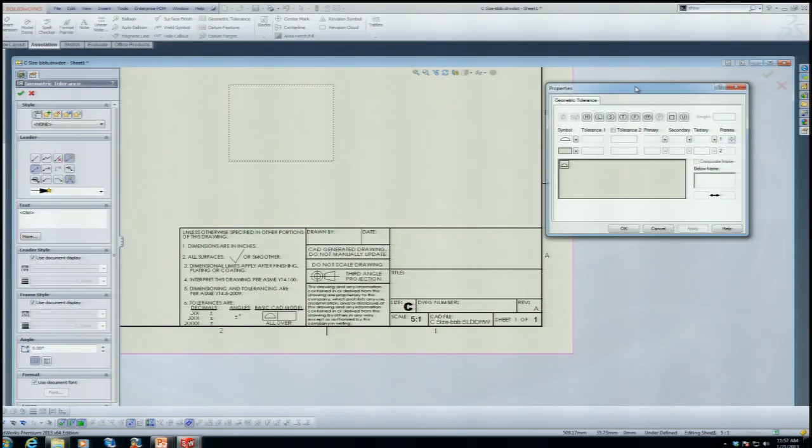Because one practice I've seen a long time ago is it will say, all measurements to be plus and minus blah, blah, blah. So basically it was saying if I take any linear measurement in the model, that linear measurement should be a such and such tolerance. But then how do you do the stack up? You're taking random measurements on the model. There's no way to measure that and control it.